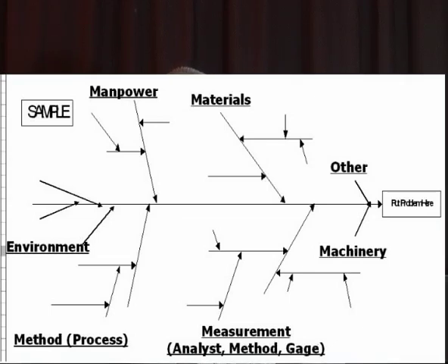As in the case of all investigations, they look at the Ishikawa fishbone and the contributing elements, the 5 M's and the E. In other words, the materials, the manufacturing method, the machinery, the measurements, the manpower, and finally, what is loosely termed as environment. Please understand, environment does not necessarily mean temperature and RH. It also includes everything else in that particular measurement space.